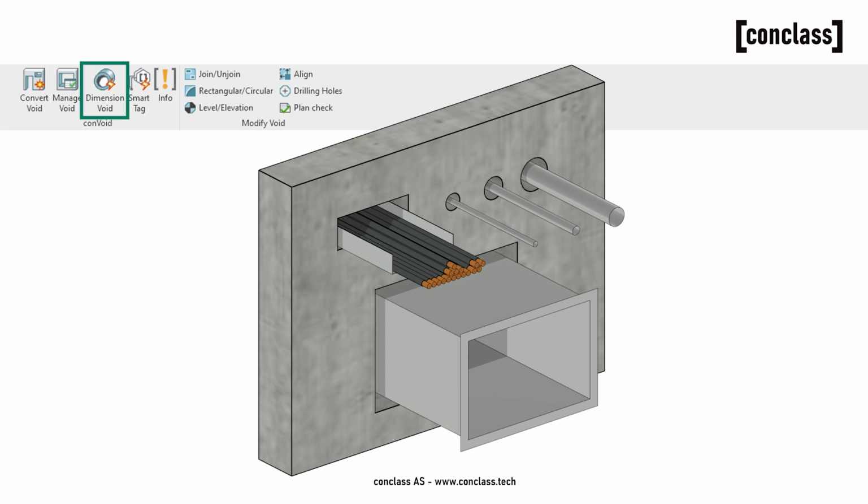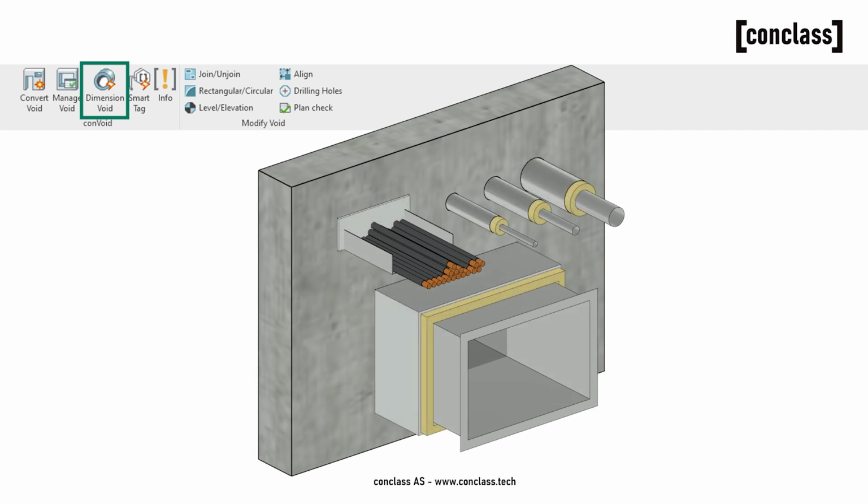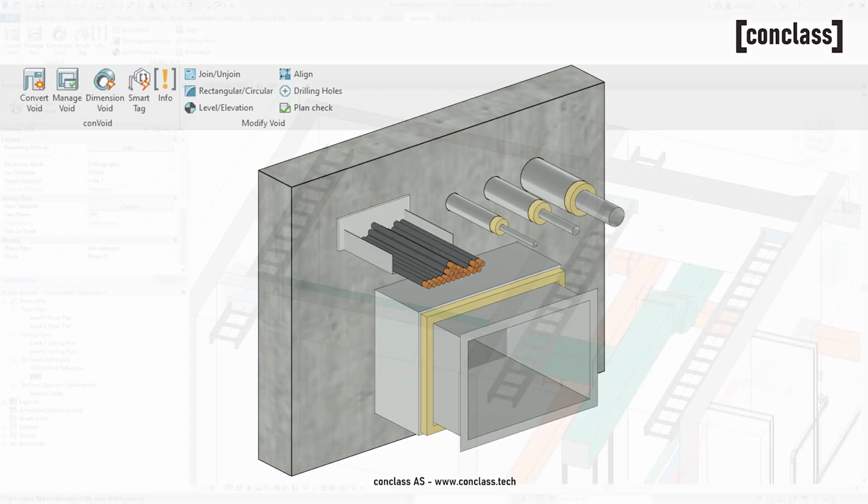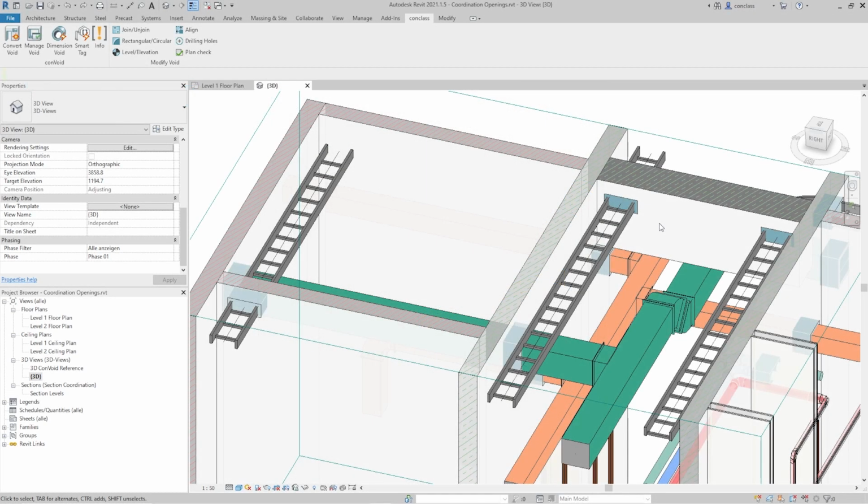openings to meet your specific project requirements, such as the ceiling requirements for penetrations to prevent the passage of fire and smoke. We strongly recommend using this feature if your project requires varying oversizes or fixed sizes for different MEP systems. To illustrate how to set a specific oversize for a selected group of openings, let's use the example of cable tray openings.